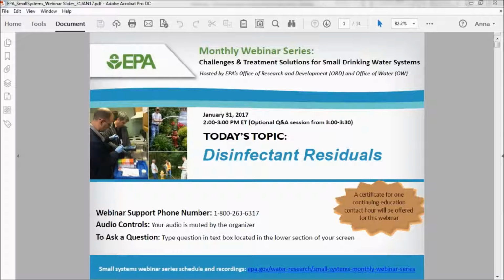As far as a study on sampler error, we haven't conducted a study ourselves. A lot of the different items that I discussed have come from manufacturers' standard operating procedures, and also training that manufacturers have done, and also personal experience. Really, it's hard to say that this issue will give you this amount of error, or that issue will give you that amount of error. It's the culmination of various issues that will compound and give you more error. So it's just best practice to follow all the guidance or best management practices I discussed.